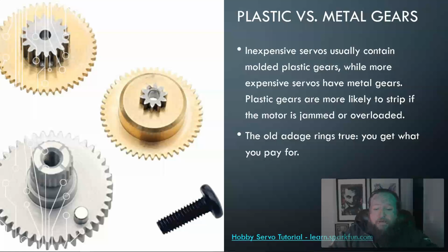But the metal ones are more expensive. So if you're doing a basic project and you're not expecting a lot of torque beyond the requirements of what it says for the actual device, then you're okay. But if you do expect more, then maybe investing more money for just those components, ones that have metal gears in them, will be better just because it can handle higher levels of torque in that design itself. So that's balancing back and forth.